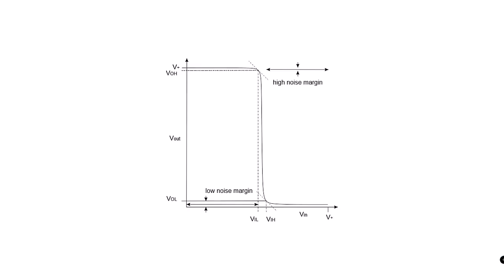This transfer curve shows the relationship between input and output voltages on the inverter. The basic shape of the transfer curve shows that at low input voltages, the output voltage is high. It very rapidly translates to a low output value. Only a very small range of input voltages put the output in this X or unknown range. Noise margin is the difference between the worst case input signal and the worst case output signal.